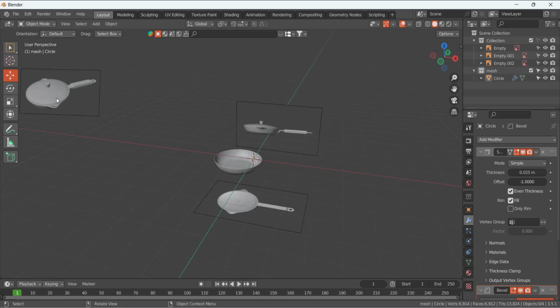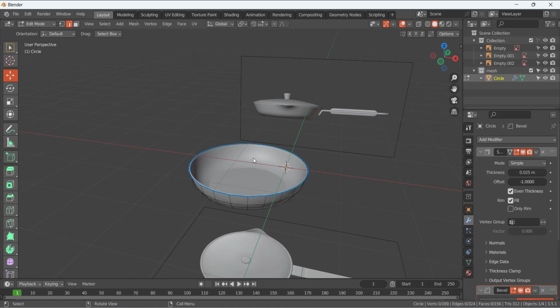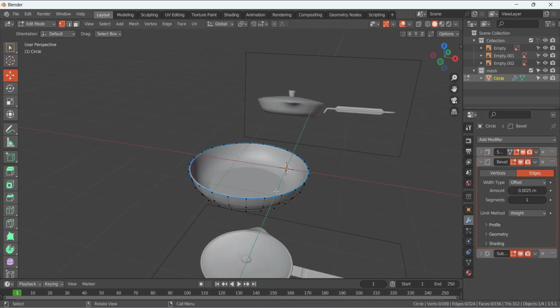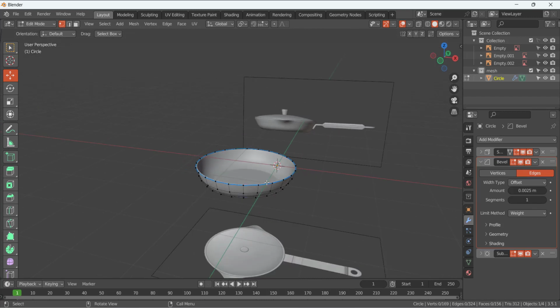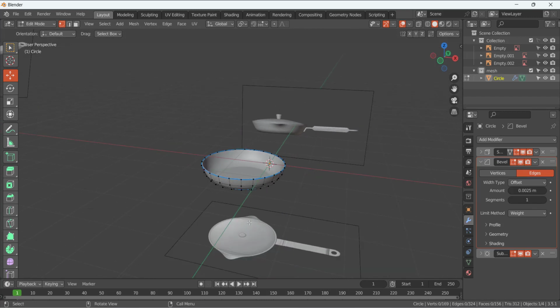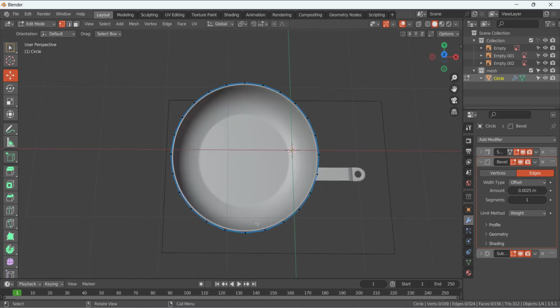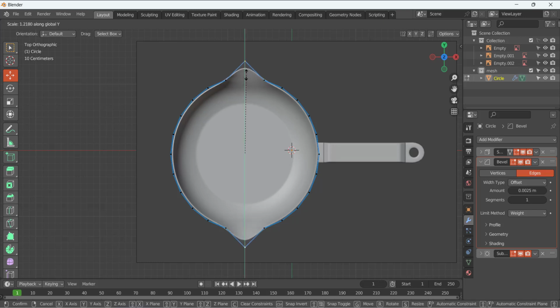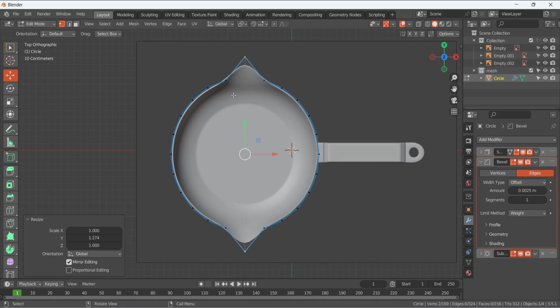So this part is complete, and one thing is left, a very important thing. So basically, we have to add this shape like that, the shape which we have here at this point. Okay, so press 7 on the top view, and we are going to select this one and this one, these two vertices, and we are going to scale it around the y-axis. So S and Y, like that. So we have this shape that matches enough,